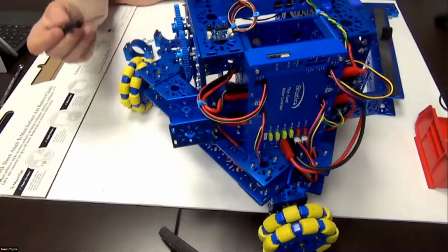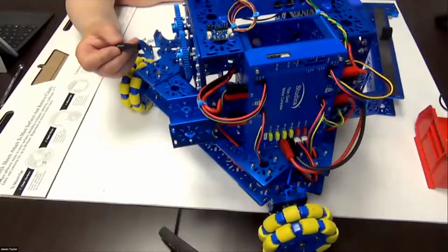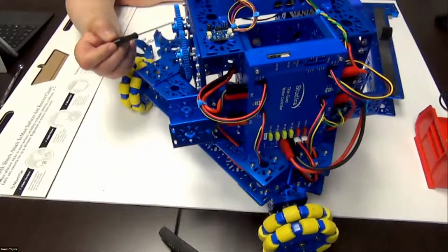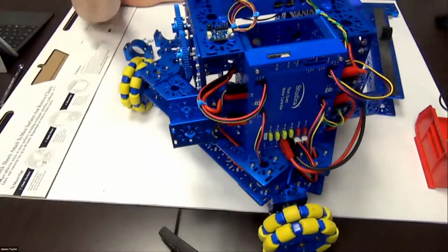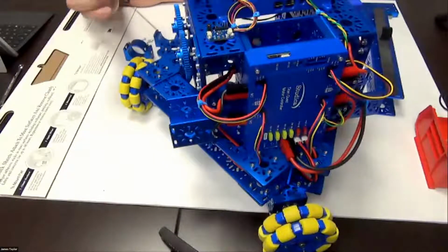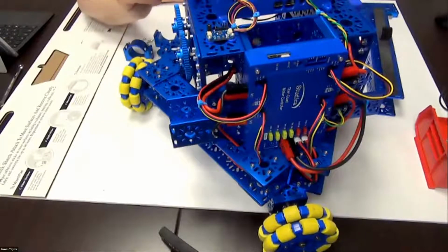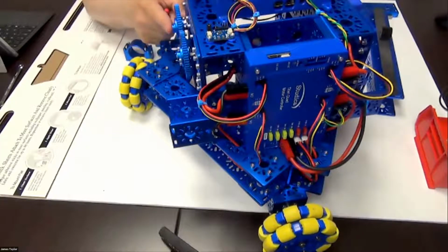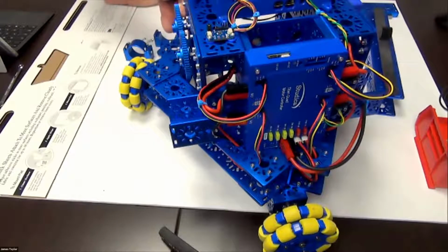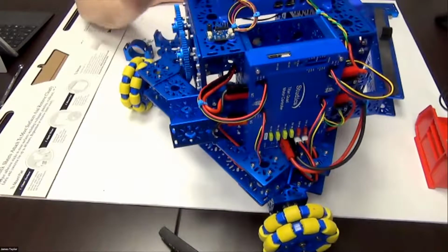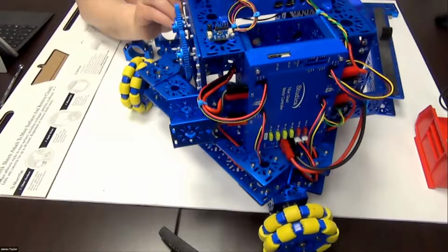Okay, so just a couple things here. It's a little hard to see, but I'll show you in a minute that on these gear systems that we put here, and this is the first one right along down here, that you're going to have on one side of the elevator, we actually doubled up on the shaft hubs. So we put one shaft hub on this side of the gear and one shaft hub on the other side of the gear. And to do that, we did actually use a 2mm spacer in here, and we used a 12mm socket-headed cap screw. Why did we do that?